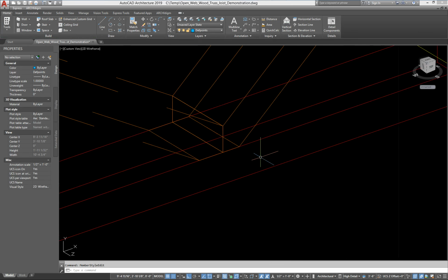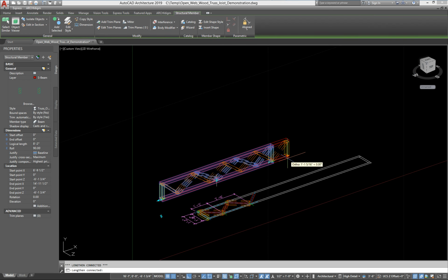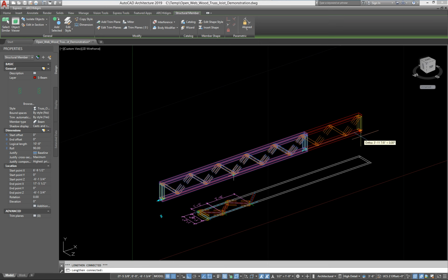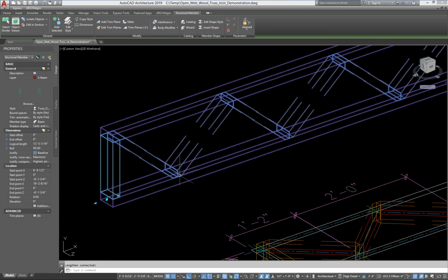All right, so here we go. It's repeating in here, so if this has been done correctly, as I pull this out, notice it's adding members, but they're scaling. And you can't really control how that scaling effect occurs. It's not as sophisticated as, say, a curtain wall. So it's just going to reach a certain point here. I don't know what the math is, where it just adds another one. It is based on the distance here, so it's the length that it's reading.